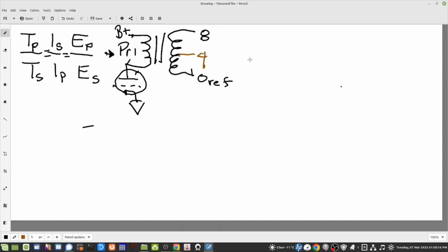So, let's get started. Oh, before we get started measuring, I'm getting excited to measure. Let's get started by looking at the turns ratio: the turns on the primary over the turns on the secondary. That fraction is N, or the turns ratio. So if our primary turns were 14 and our secondary turns were 2, we'd have a turns ratio of 7.